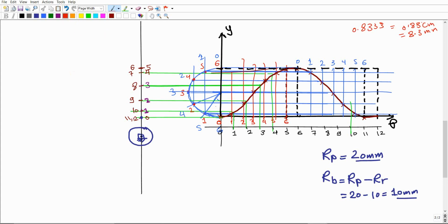So you're gonna use the protractor starting from the vertical line, and then from the center point, you're just gonna measure an angle of 30 degrees to draw this line. And make sure that you try to have this line as long as you can, a very long line in this way, passing over the center point or the center of rotation of the cam, in such a way that this angle should be 30 degrees. Then you're gonna measure another 30 degrees this direction, this way. You're gonna measure another 30 degrees and draw another line from this 0 point or center point in this way.